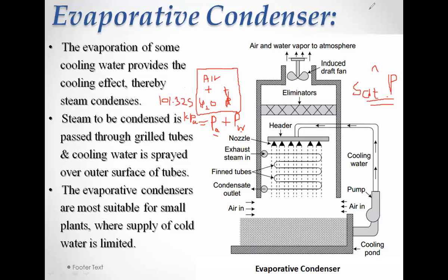So if you see the construction of a cooler, at your face we have a big fan, right? So there is a fan at your side. Okay, so I will draw somewhere here. At the back side we have this porous structure or porous membrane. On this porous membrane, there is also a water pond at the top. Continuously water is dripping. So water drips onto this porous membrane, and this fan causes a draft.